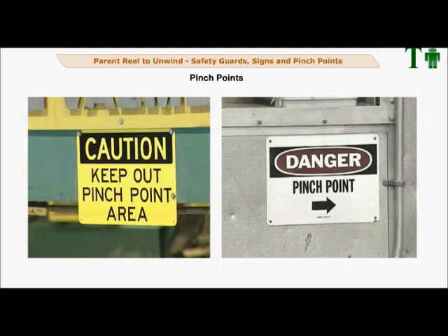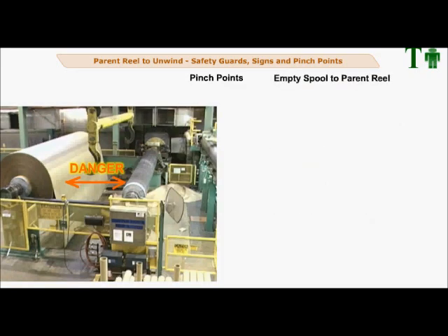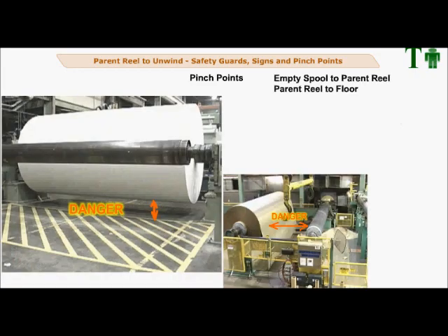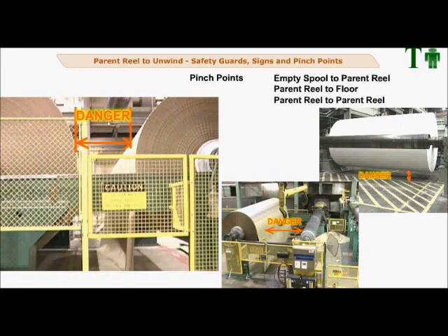You must always be aware of pinch points. Some pinch points can occur during the chucking up of a parent reel. They are located at the empty spool, parent reel to floor, and parent reel to parent reel.